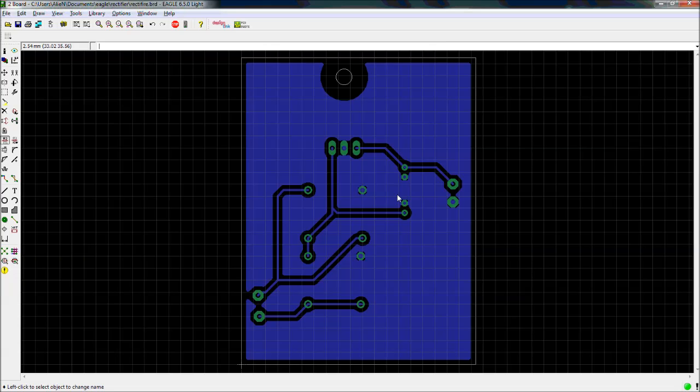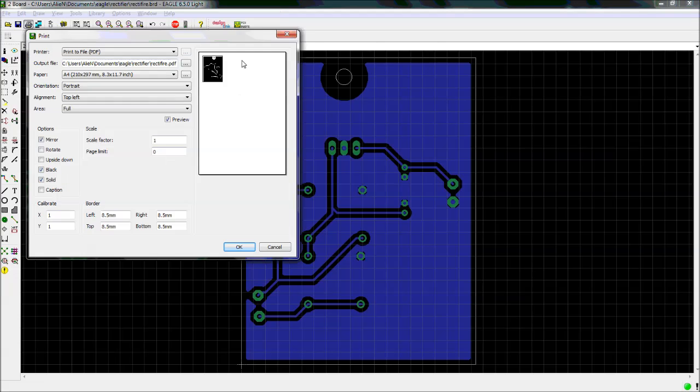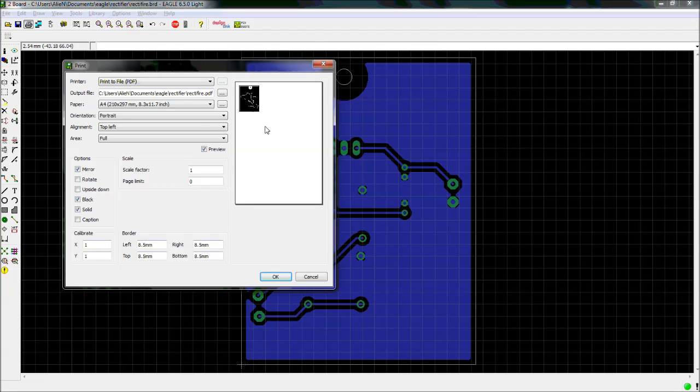We press it from the top, and the color of that paper will impress on that copper, and then we will wash off the remaining copper using FeCl3 solution. And for that you just need to print this circuit. Now you can see it in this image.